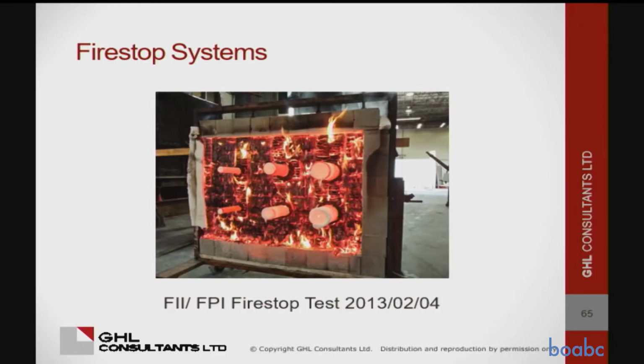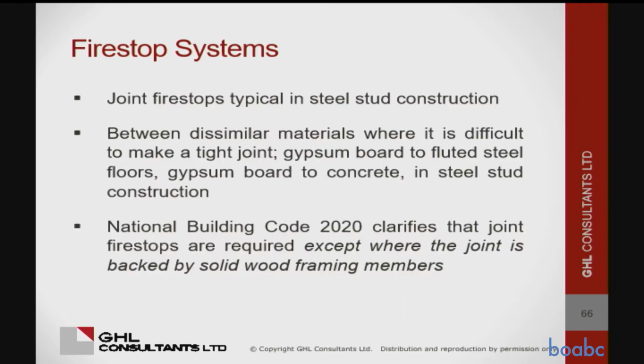And this is a fire test of a fire stop system. So we're just going to talk about joint fire stops for a minute, because I get this call all the time too. Do I need to fire caulk the joint between the wall and the ceiling? I'm like, well, not in wood framing. Don't you have a whole bunch of wood behind there?